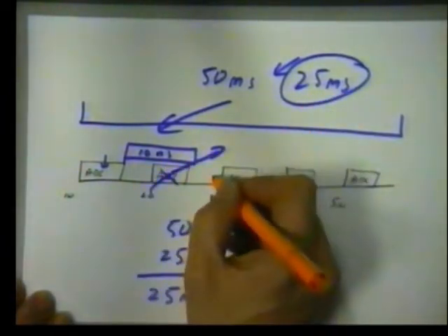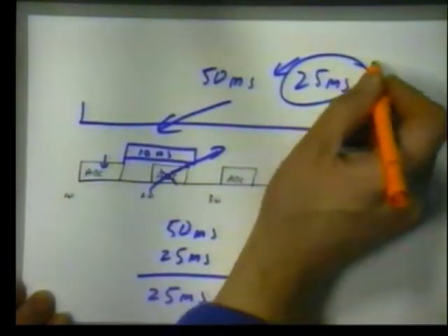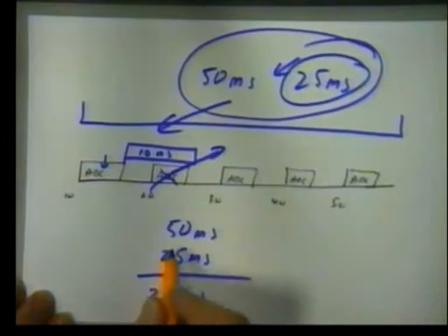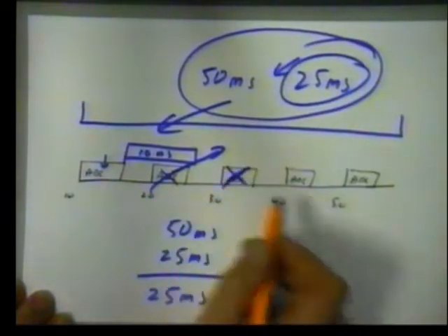So you cannot simply allocate all the remaining time to the slower interrupt, because if you did, the fast interrupt could be displaced. It could be even worse. What would happen if once a second, there was a 100 millisecond data dump to a tape streamer? For the whole of that 100 milliseconds, all other interrupts are blocked out. You cannot allow that to happen.